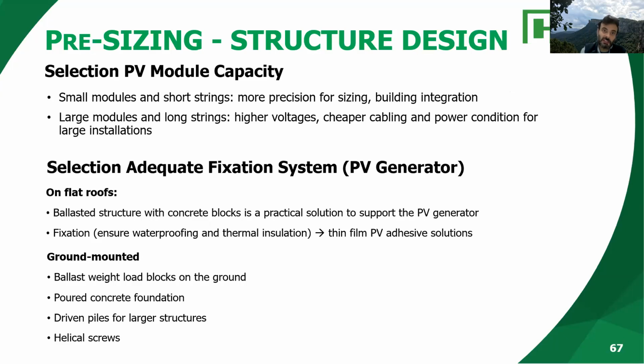For the structure design, some tips here. Small modules and short strings, short connections, will give us more precision for sizing. That will be very helpful for building integration of photovoltaic panels. If we are planning large PV plants, then we will probably be better off thinking about larger modules and longer strings, of course.